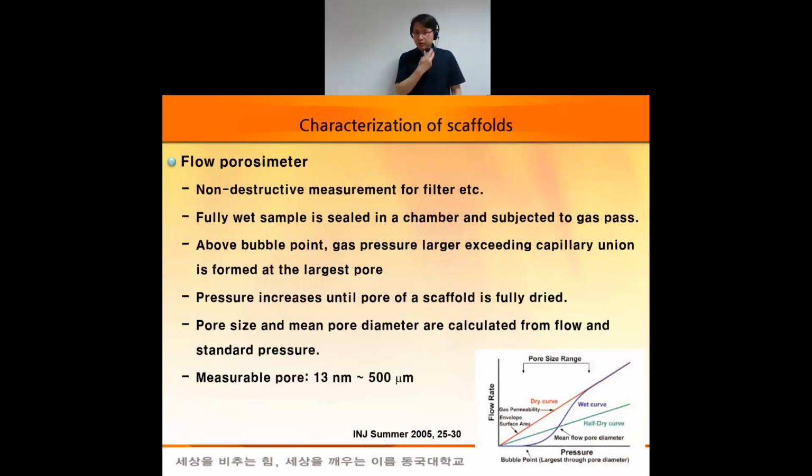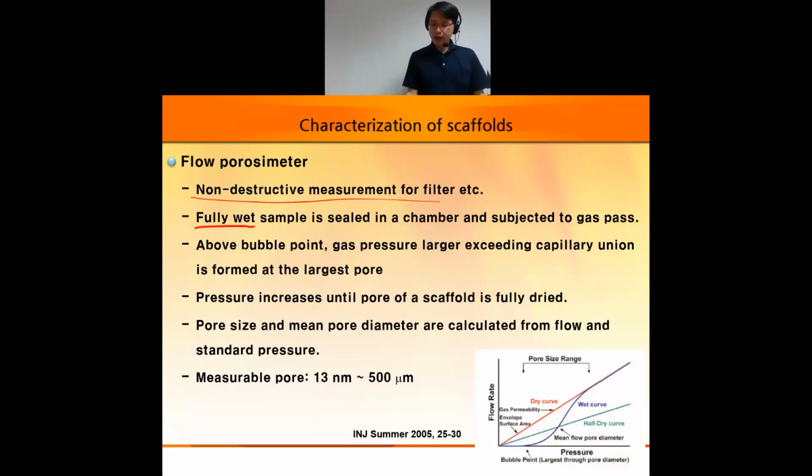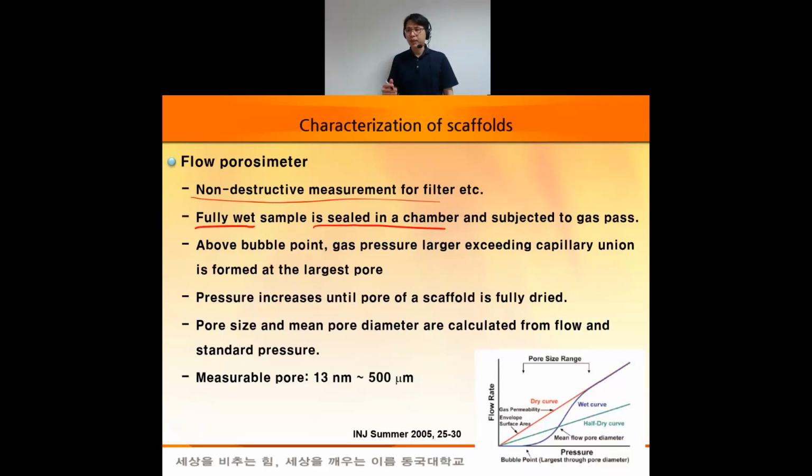The other method is flow porosimeter. It's a non-destructive measurement and it is well utilized in filter measurement. First, the sample is fully wet with water, and the sample is sealed in a chamber and subjected to gas pass. Gas passes through the fully wet sample.